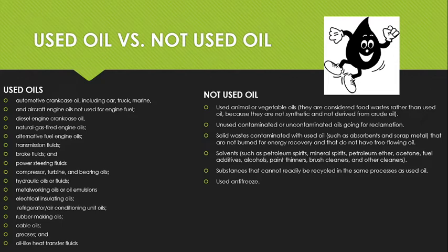Let's say we decided to send those absorbents and used oil to Midstate for recycle, or Clean Harbors for recycle. Then now those absorbents are considered used oil and they have to be managed under used oil rules, which we'll go through here in a minute. I don't know why they do this, but they actually make it more difficult and more stringent to manage used oil related wastes which are being recycled, which one would think is a good thing.